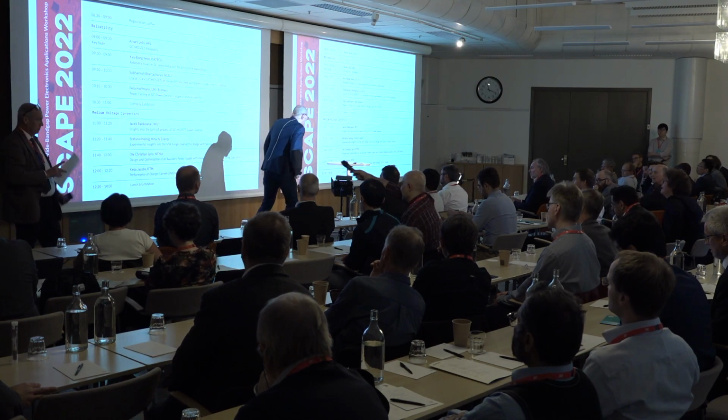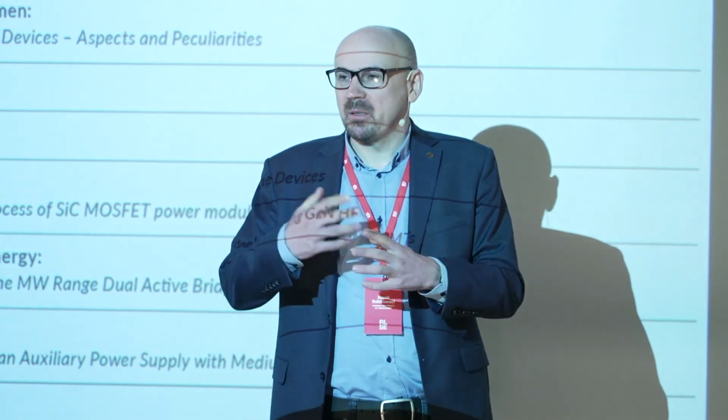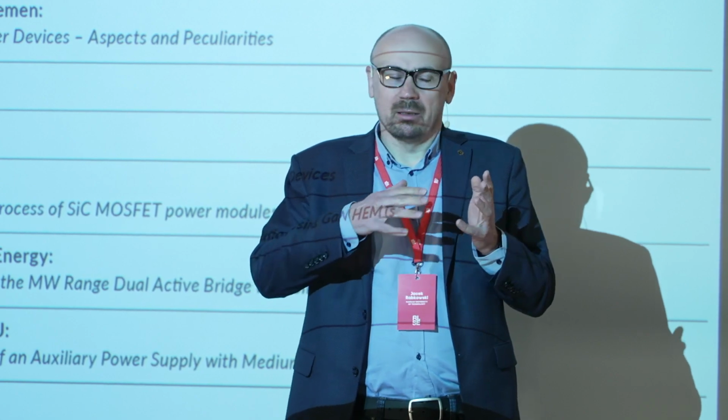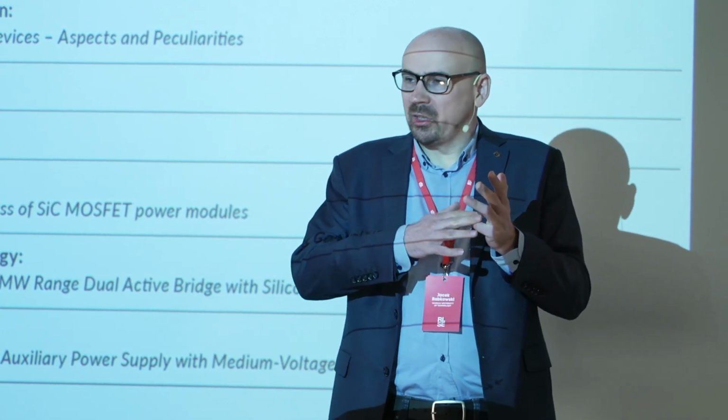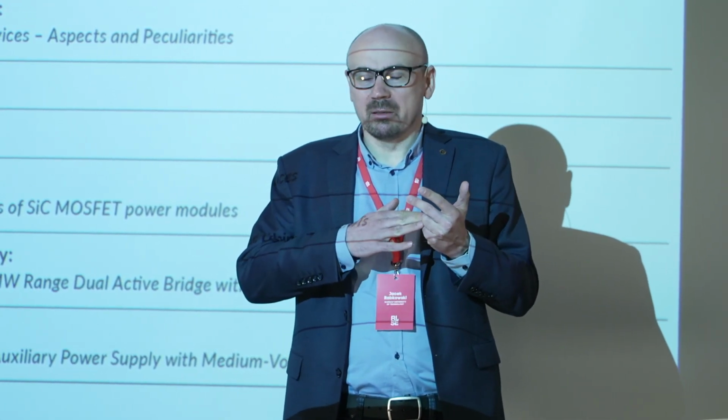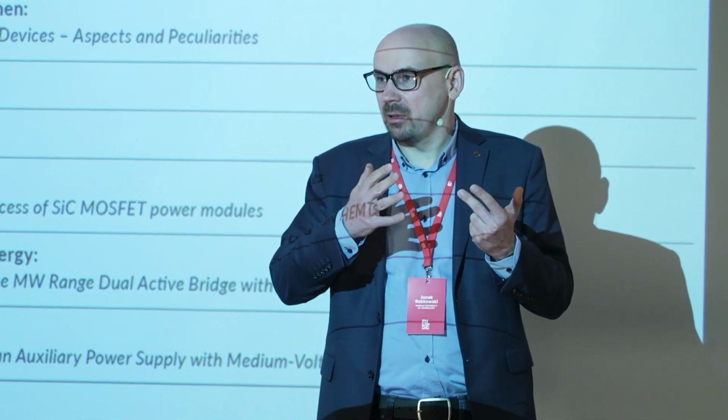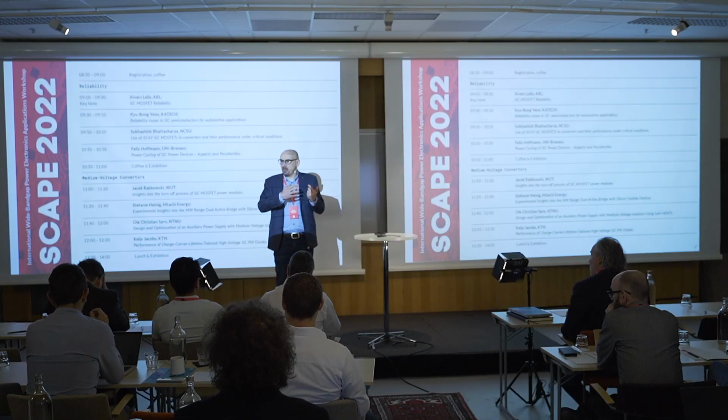Yeah, but the point is that as we've seen before, with all those things like charge traps, we realize that there are so many factors: VDS, VGS, also the shape of the gate voltage pulse, the length of the gate pulse.